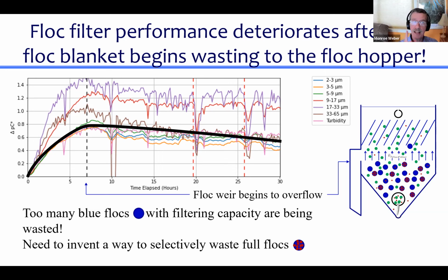But now we think that's not what's happening. What's happening is you're capturing particles on the inside. And on the inside, once you're full, there's no more space to put any more. Or as you capture particles on the inside, it's less porous, and so less water is actually sneaking up through that floc, and so that floc becomes useless because there's no water flowing through it anymore. So now we have a new hypothesis about what's limiting performance, and that gives us an opportunity.